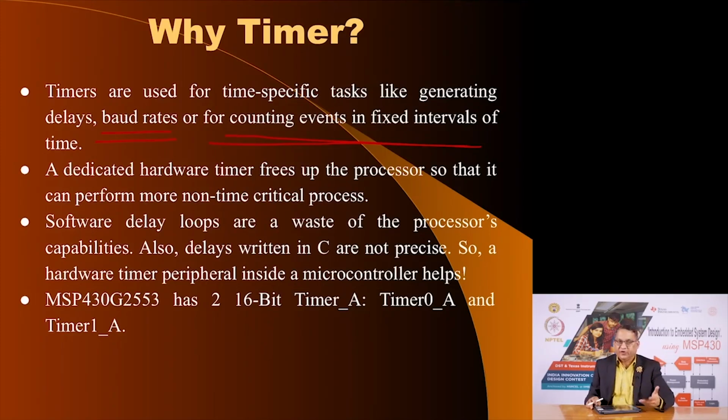You can also use a CPU. For example, one of the port pins could be connected to an external signal where you are getting pulses, and you can write a program saying, if this pulse is high, wait for it to be low, once it goes low, one pulse has been received, you can count it, and so on.